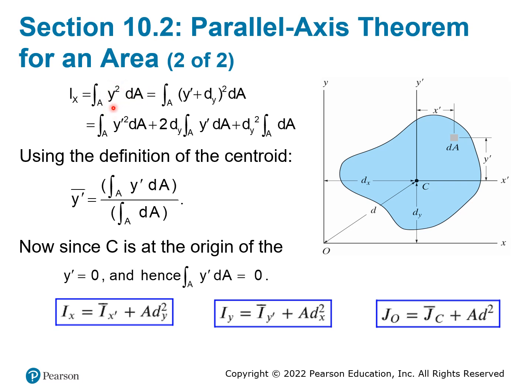And this y here represents the y-axis that you choose. It should be the distance of the centroid to the x-axis. So say, for example, look at this picture right here. We're looking for the moment of inertia of the area with respect to this x-axis. And the y is going to be defined by any position in the shape and how far that is away from this x-axis.